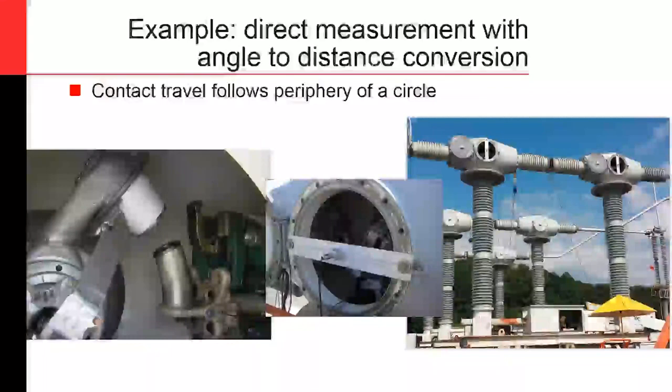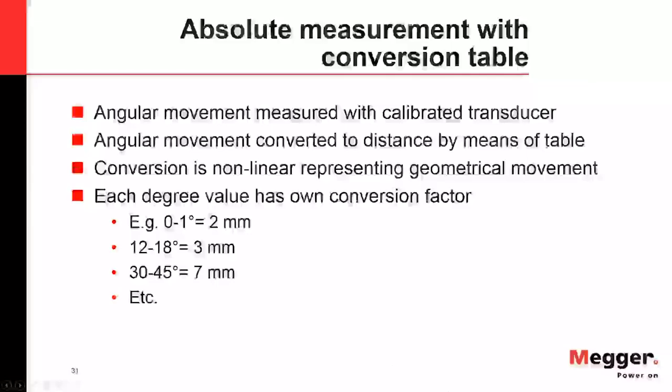And this is that SF6 circuit breaker I mentioned before. This is a 500 kV circuit breaker, 4 breaks per phase. What you do is open up these tanks, of course, evacuate the SF6 gas and hold it during testing. You open up these tanks and then hook that transducer right on the center there, and that transducer would rotate along with the interrupter. But what you want to do is convert that rotational value to a linear arc length value to get the interrupter actually moving back and forth on the left there.